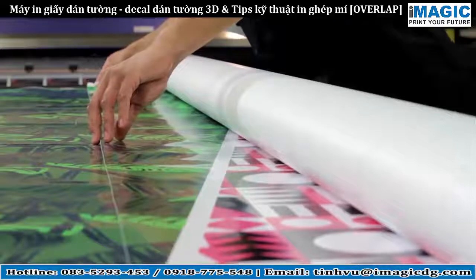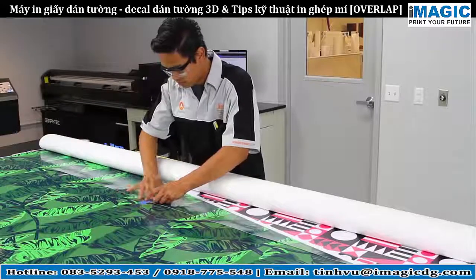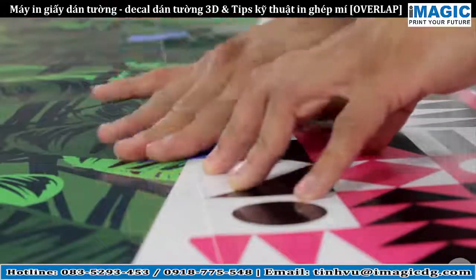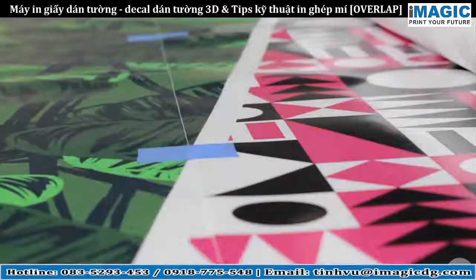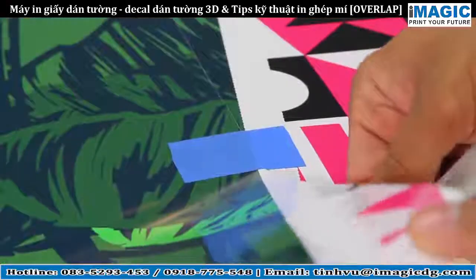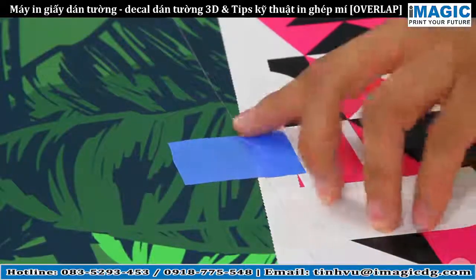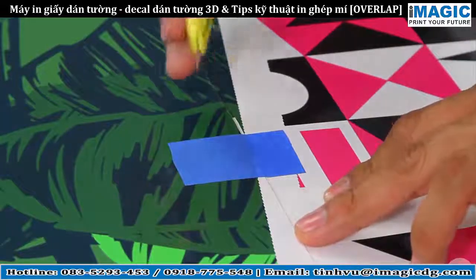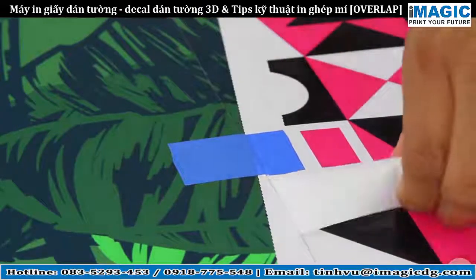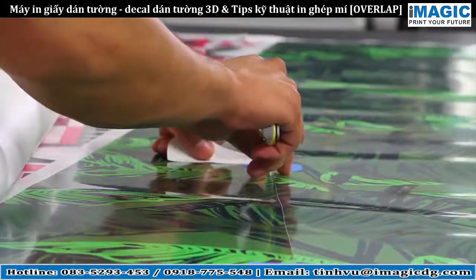Carefully align the overlaps of two adjacent tiles and apply small strips of blue masking tape across the seam every 2 feet down the graphic. To prevent cutting on the real graphic, use a small piece of release liner under the blue masking tape. Cut the masking tape along the edge of the overlaying tile. This will serve as registration marks for installation.